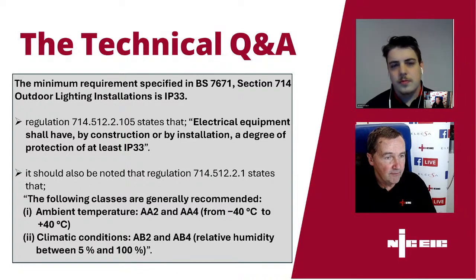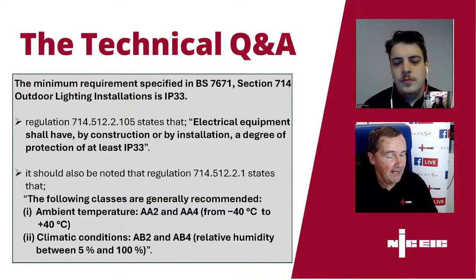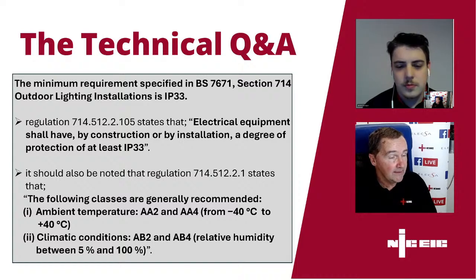If you've modified circuits 1 and 2 but not circuits 3 to 8, and then you've added circuit 9, you would put a date for the next inspection based on circuits 1, 2 and 9, because that's all your certificate would cover. The date for the next inspection on circuits 3 to 8 should still be based on the original installation certificate which covered that work.